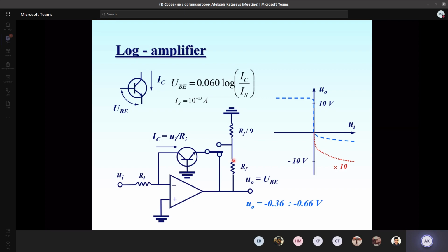So I may add some scaling circuit which allows me to scale my logarithm. This is a logarithmic amplifier. Make sure that they are inverting amplifiers, so if you are going to use a positive voltage, we have to invert the output, but nevertheless it works pretty well.